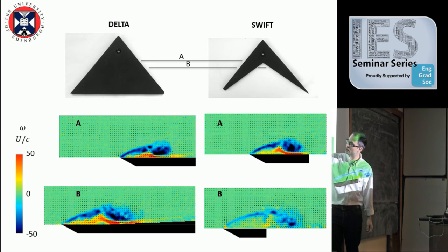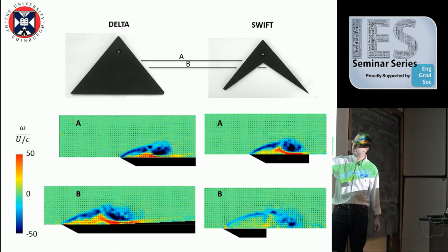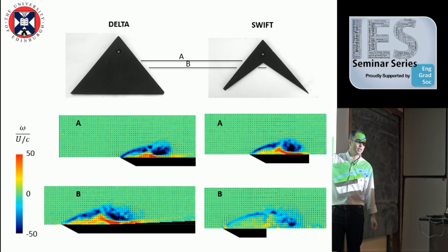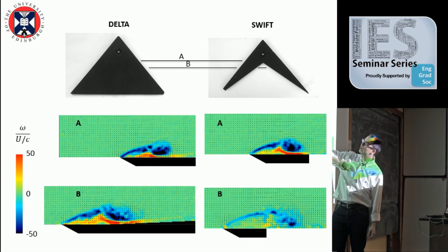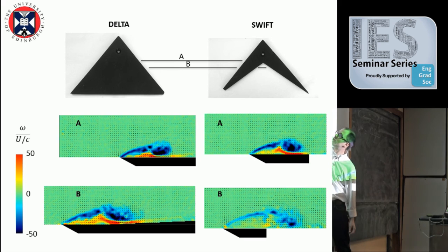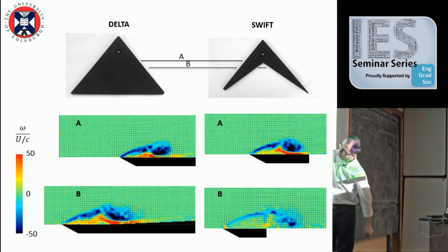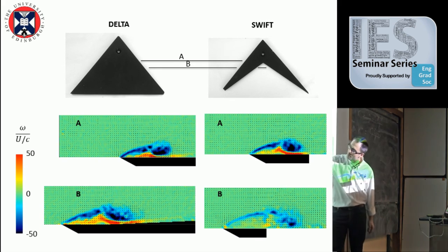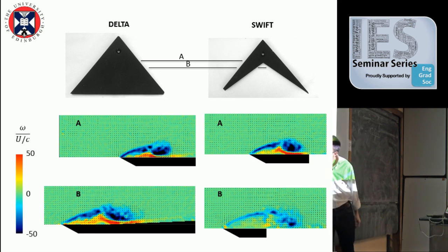So you have one vortex which is going up to here, but then on the way back it generates a counter-rotating vortex. That's what you find, okay? So this one is a cross-section, sorry, pardon me, I should have probably mentioned before, there's a cross-section at this level of your delta wing. And if you move from A to B, you basically increase these sides, you move from here to here, and not much has changed. You see the same behavior. You have this large vortex rotating in this direction. Some air comes inside from here and rotates in the other direction.